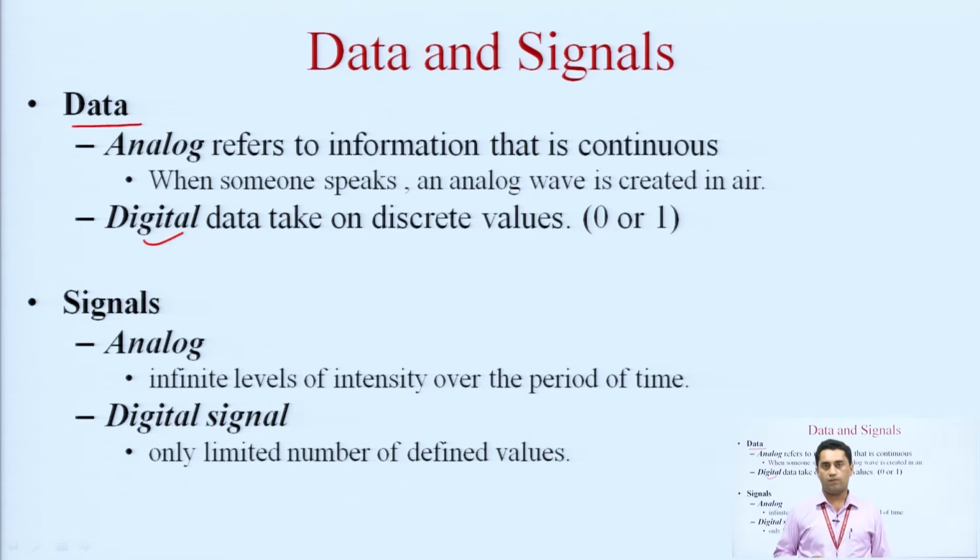In the same manner, we have two types of signals, analog signal and digital signal. An analog signal is one where we send our data in the form of sinusoidal waves, which are continuous in manner. With digital data, we take 0 and 1 bits and convert them into an analog signal with the help of a process using sampling and quantization. When we transfer digital data in the form of digital signals, we have other encoding schemes.